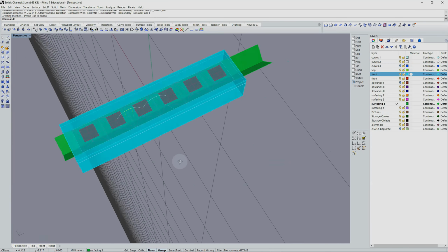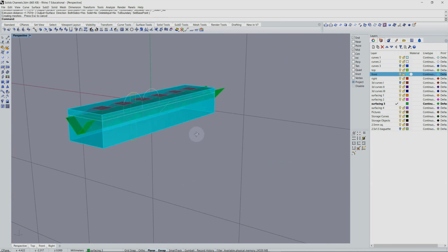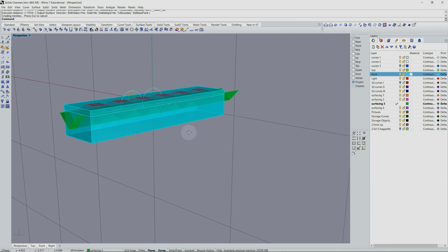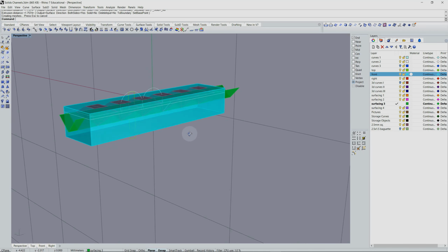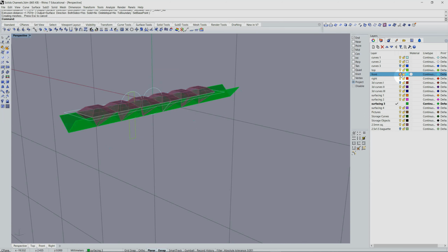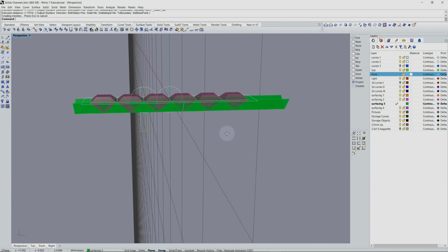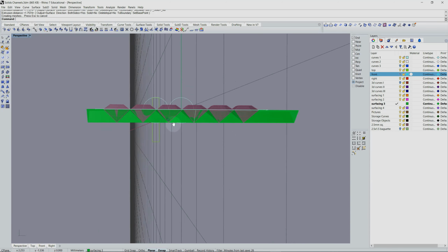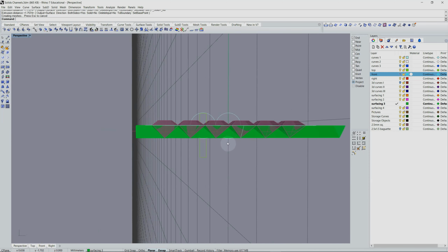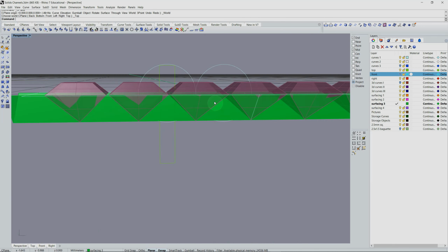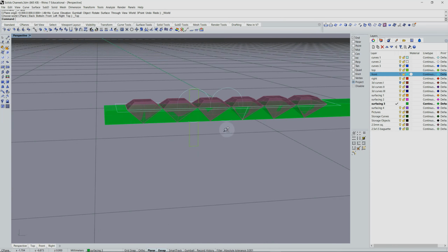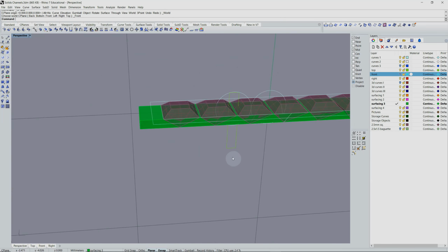I need to establish a cutoff depth for the pavilion setting. In preparation, I'll revisit the Layers panel and turn off the light blue layer to simplify my scene. I want to cut off the stone seat at a level about 1/3 of the way down the pavilion of the stones. I'm going to pop back over to top C-plane for a bit and take a closer look at these pavilion depths. I'm going to use a cutting plane to take this measurement, so returning to front C-plane,